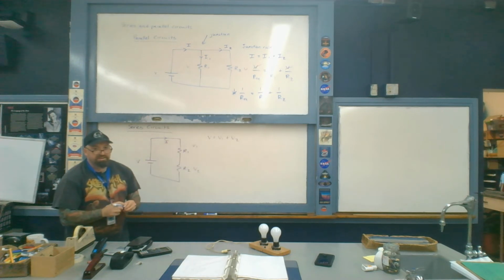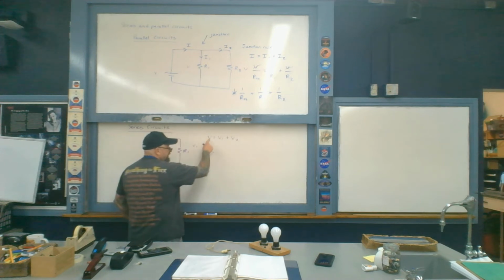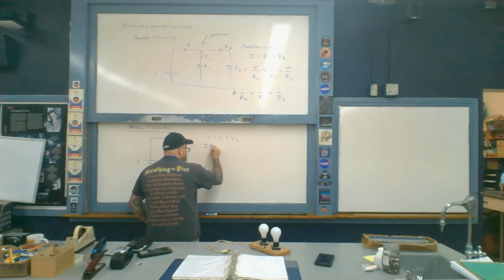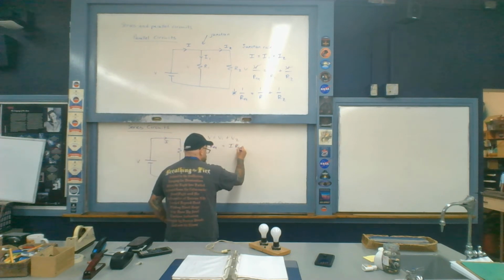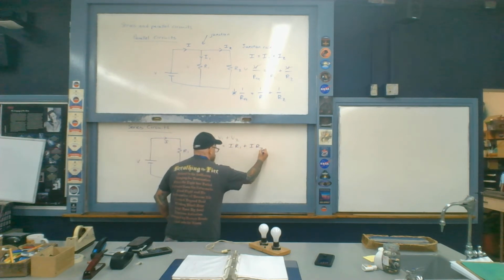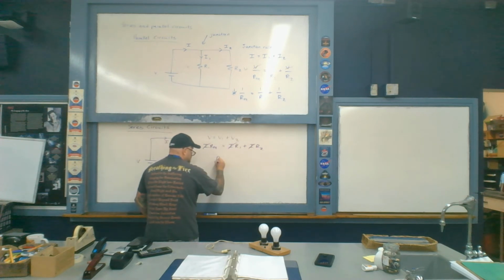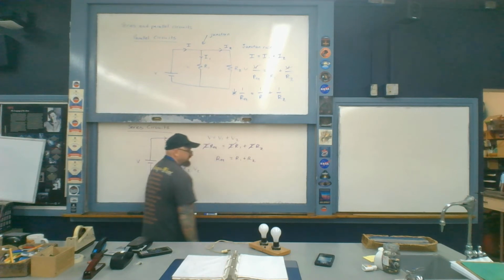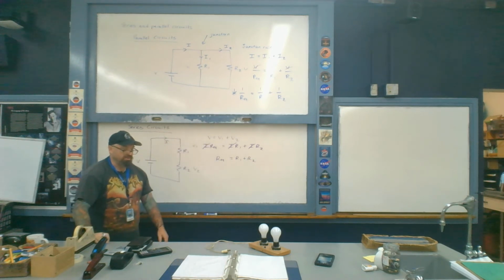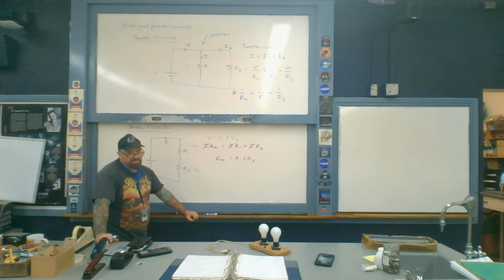Go ahead and replace these V's here now with I times R from Ohm's law. So on the left-hand side, this is I times what we're trying to find now, the equivalent resistance. This is then I times R1 plus I times R2, and then all the currents I cancel out. So then therefore, the equivalent resistance is R1 plus R2, like so. So you add up the resistors then in order to ultimately calculate the equivalent resistance for a series circuit.